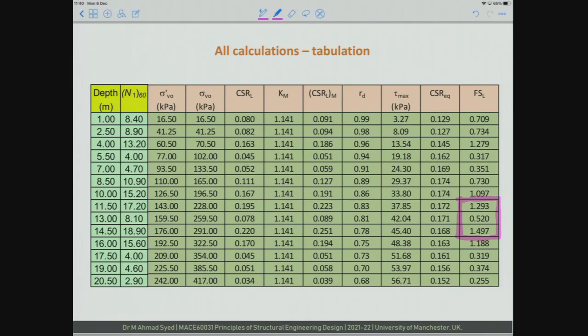Now think about the fact that you are trying to place a pile foundation, and you are saying that yes, the pile foundation is likely to be 11 meters deep, but that will be a bit risky because from here you have this layer likely to liquefy, although it is not directly liquefying, but indirect liquefaction of this layer. So again, that is something you may need to be mindful of: you may have a very weak soil layer sandwiched between comparatively stronger layers. The stronger layers may not liquefy on their own, but you may have some effect of liquefaction on them because of the comparatively weaker layer.